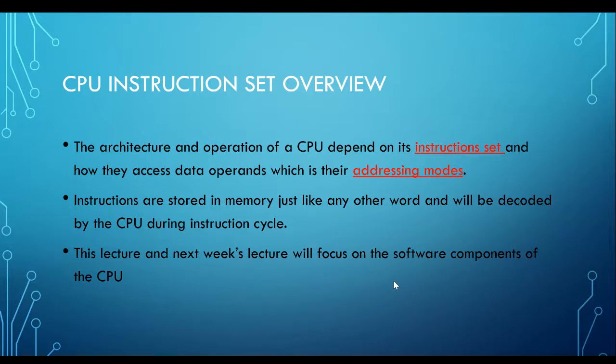I'll give you an example that I always give. Let's say you are blinking an LED again and again. These kinds of simple things you can write in C programming and compile into the memory, and it will start from the boot address. You go to the memory, and it will just keep repeating. When you do programming, it is very easy for you. All you need to do is while(1). It will keep on repeating again and again. But in the case of assembly language, we want to know how it is done.